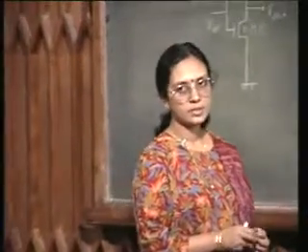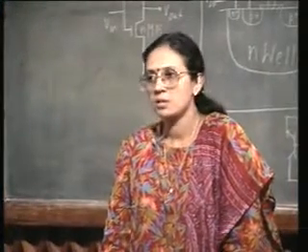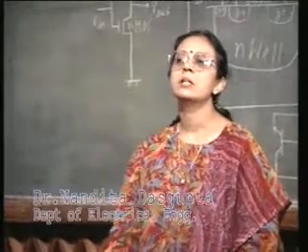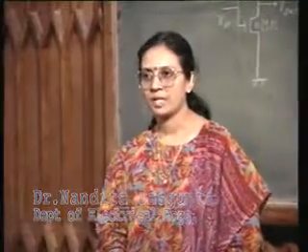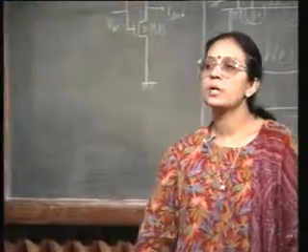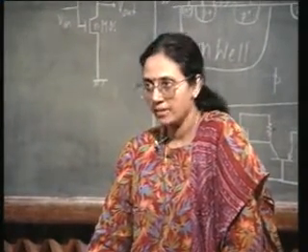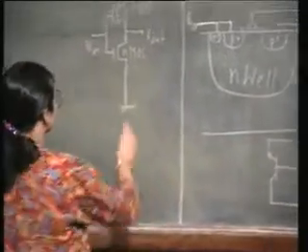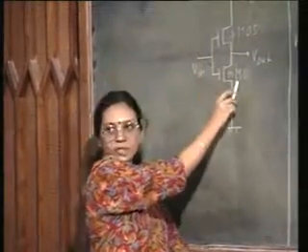We have been discussing the problems in CMOS, basic CMOS technology. Now, one of the serious problems in a CMOS circuit is the problem of latch up. This problem is inherent in a CMOS because we have both a P channel device and an N channel device. Okay? And a basic CMOS inverter is connected like this. You have the PMOS device and you have the NMOS device.